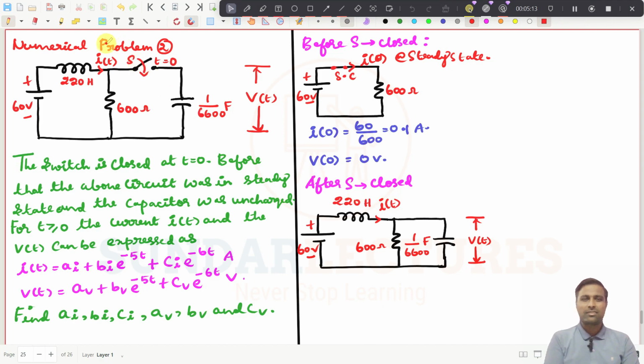So here they have given you I of t and V of t, but I am just assuming this to be I1 of t, and this I am taking to be I2 of t. If I want to find the value of I of t, it is now easy, right? So I of t will be equal to what? Simply I can write it as I1 of t plus I2 of t by using Kirchhoff's current law. It is very simple. This is coming in, these two are going away, so I can write it like this.